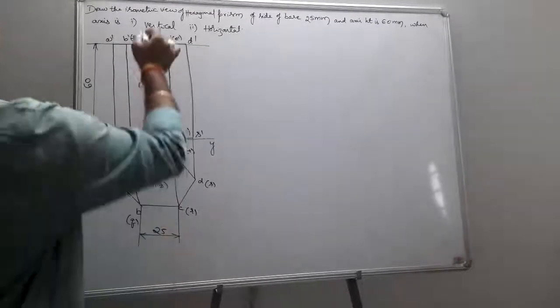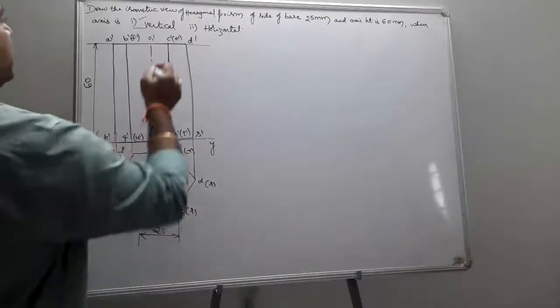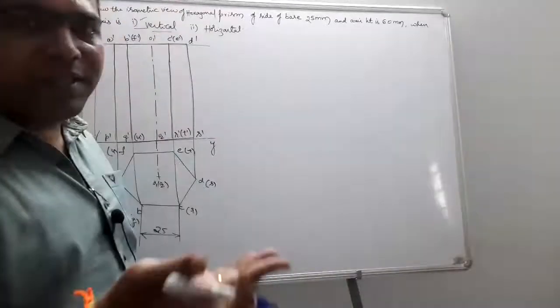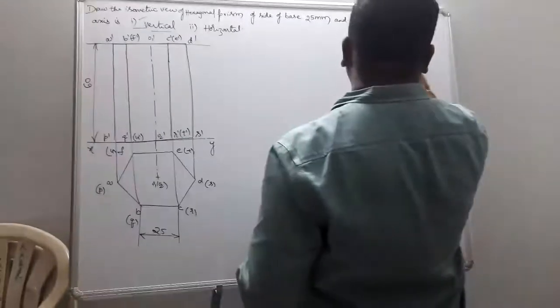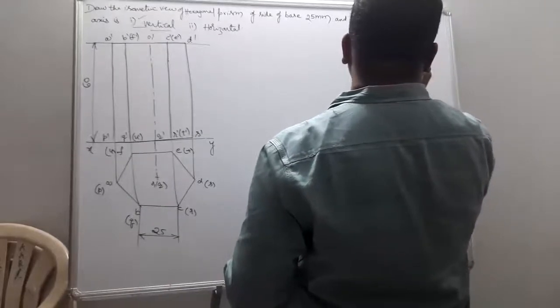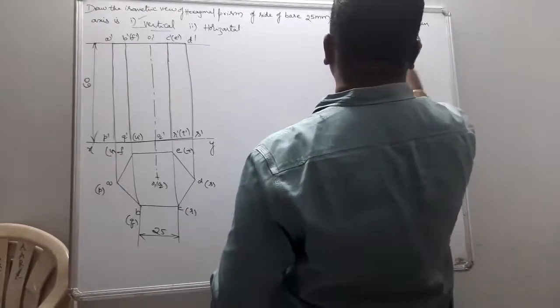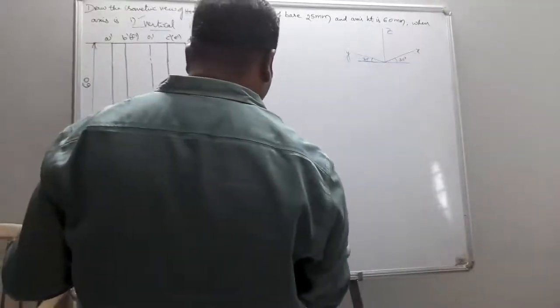Now I just consider vertical; you do horizontal. I constructed it for vertical, and you do horizontal as your assignment. I make my axis vertical. Axis vertical means the base becomes parallel to HP, that means the base is parallel to XY. What are the isometric axes we have? We already know this. This was 30 degrees, X, Y, and Z. For horizontal, which axes are considered? X and Y axes are going to be considered.